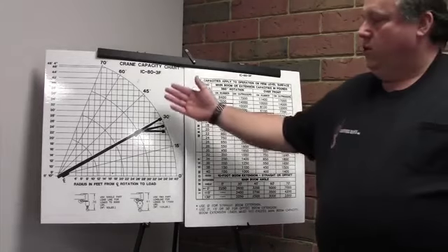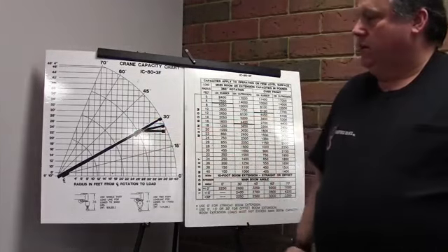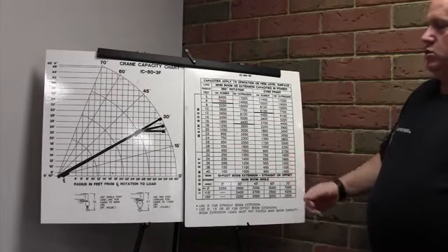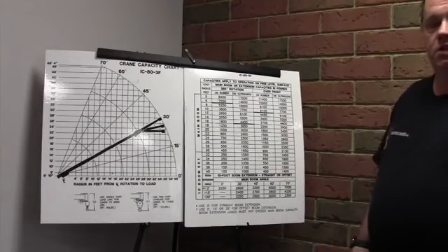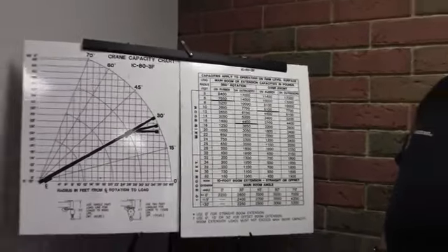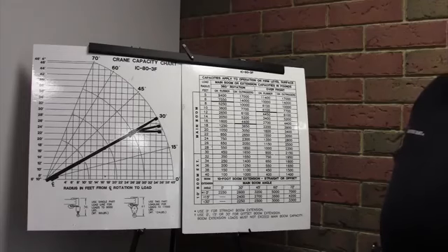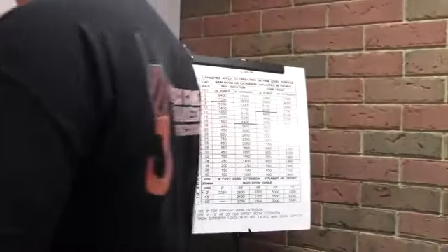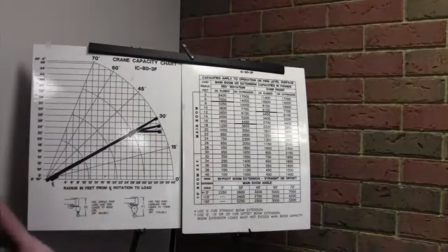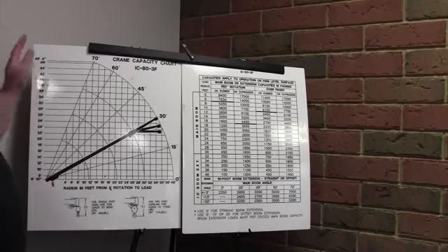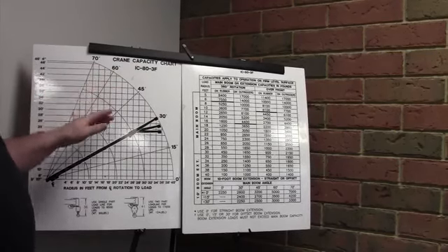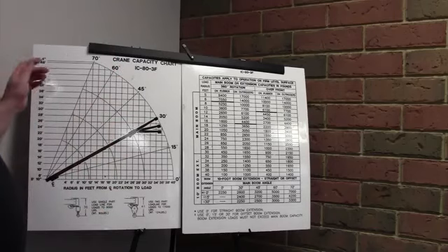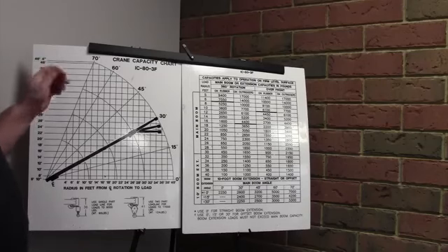The first one is the graphic representation of what the crane looks like with the boom at different lengths and at different angles. And over here is the chart that is used to interpret the graphic representation so that we can calculate the load capacity of the crane. These particular charts on the board today are from a Broderson IC83F. Each individual crane that we deal with is going to have its own load chart, so we're not intending to give you a one-size-fits-all load chart. What we're trying to do is explain the ways in which we use load charts